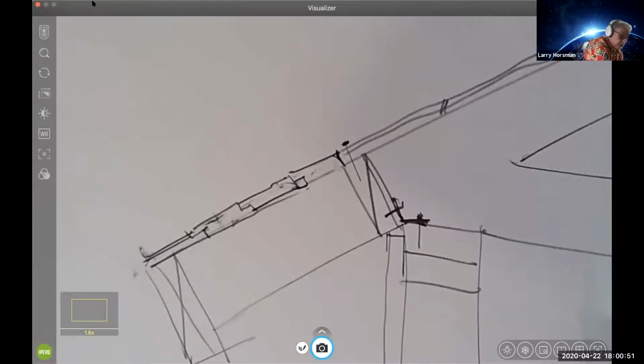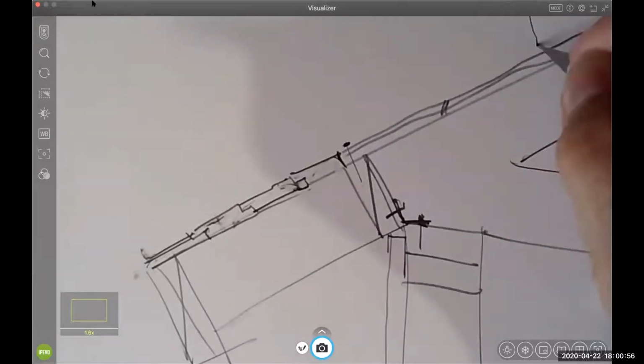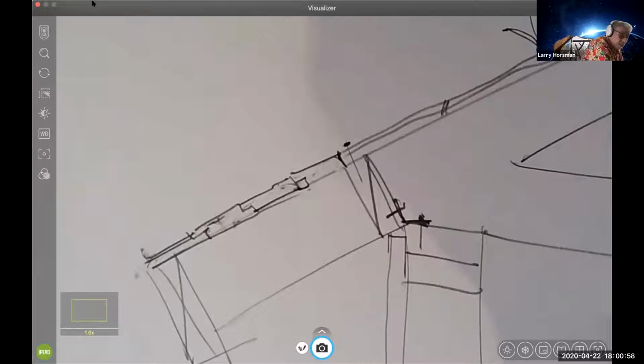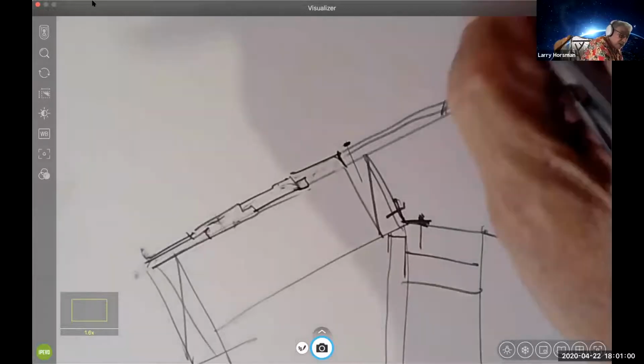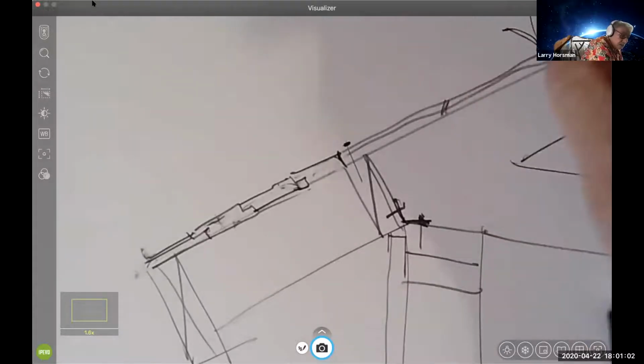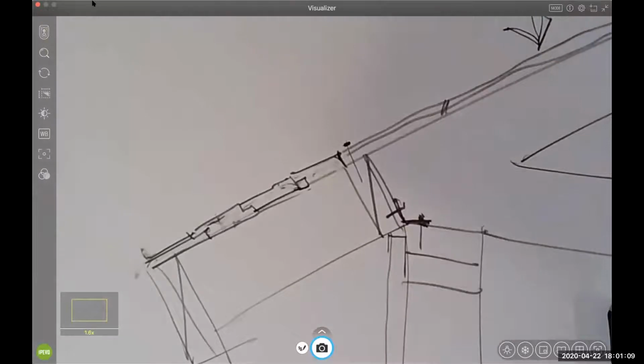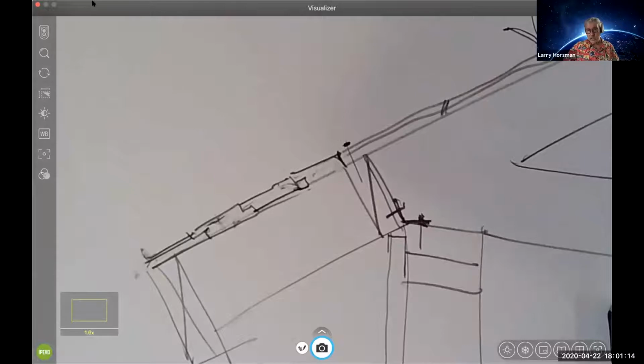because what kind of plywood are we using here normally? OSB, 3/4. Yeah, either CDX or OSB. And is that what you want to see when you're looking up? You're either looking at the C side or the D side on the plywood, which allows open knots. And so normally people don't like that look. And OSB doesn't weather real well when it's exposed. It kind of puffs and it starts to flake.